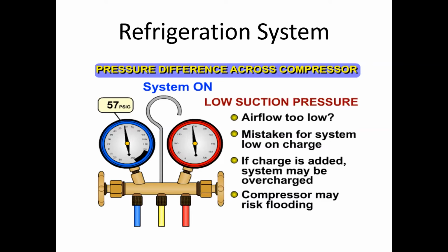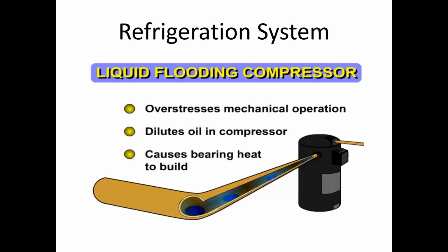So low suction pressure is often mistaken for a low charge. First, check your airflow. Having insufficient airflow or not enough air through that coil can make your suction pressure low and make you think that you have a charge issue. All right, talked about this already, right? This is what happens when we flood our compressor.